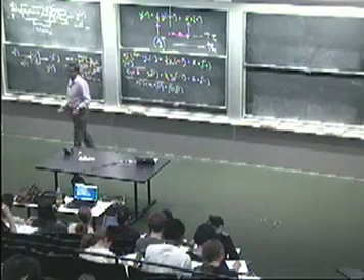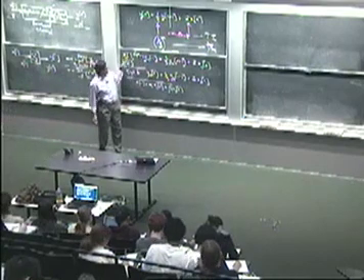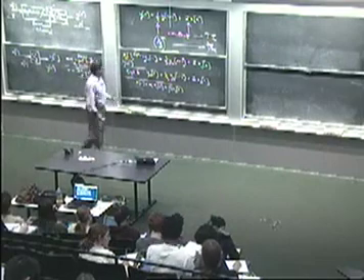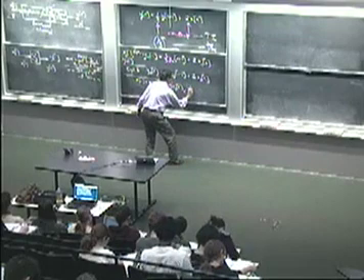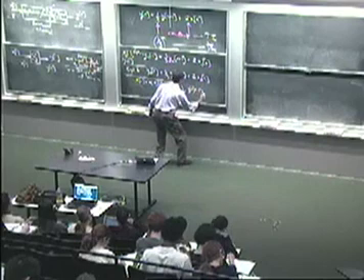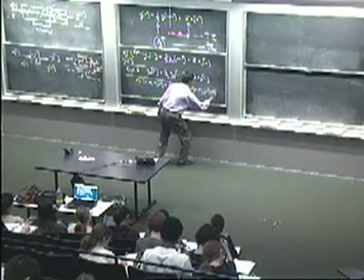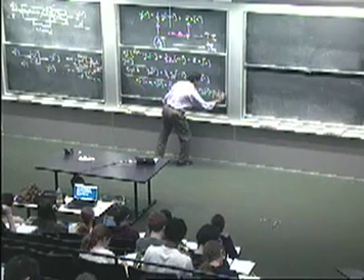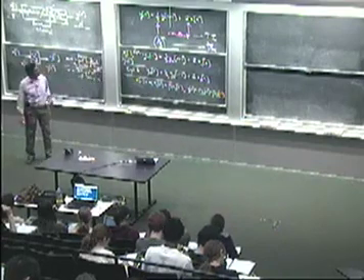So here's a new experiment in which I'm going to use an input that's a linear combination of the previous two inputs with some arbitrary weights, alpha and beta. And the question then is, the corresponding combination of the outputs in the previous experiment, alpha y_A[n] plus beta y_B[n], does this x[n], y[n] pair satisfy the same equation?